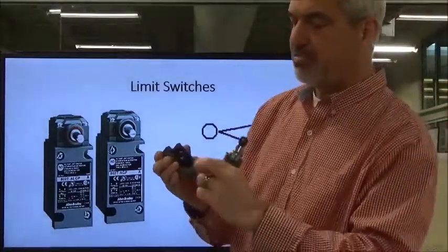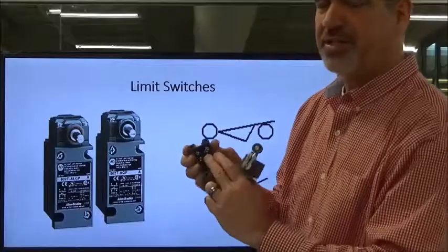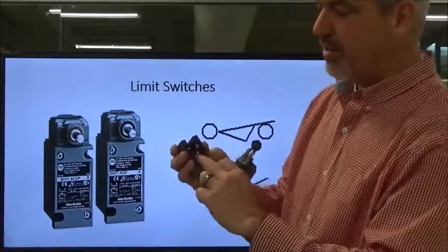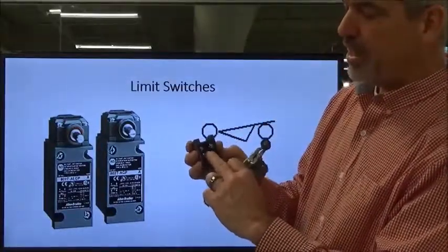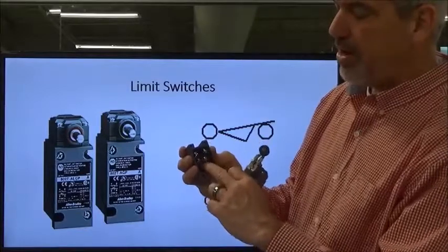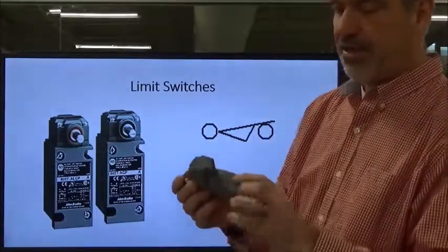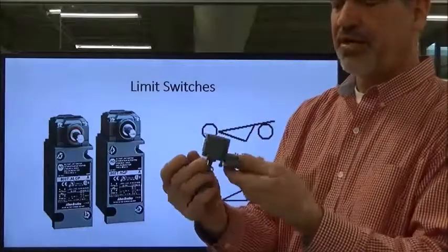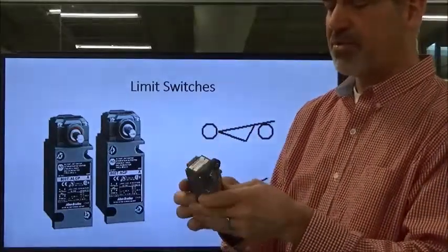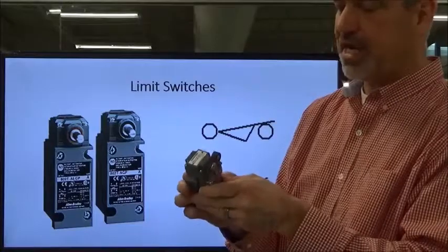And you run your wires, you park your wires right here. Just showing you, you're not going to get a whole lot out of this, but you land your wires right here, your hot wire, and then you have your wires coming in and out of your contacts. And these are little prongs, like plugs right here. It's real easy. If part of the switch gets damaged, you don't have to replace the entire switch.